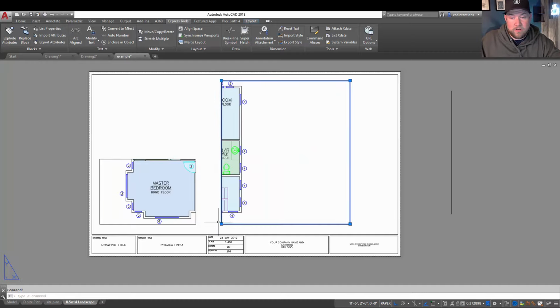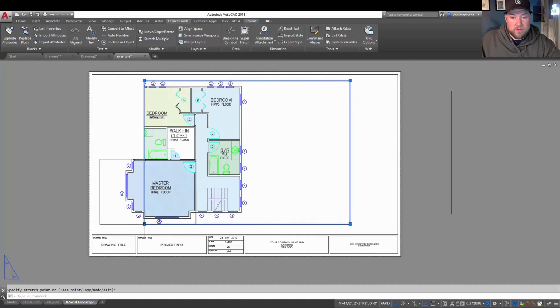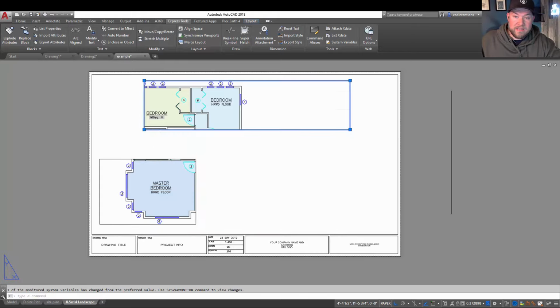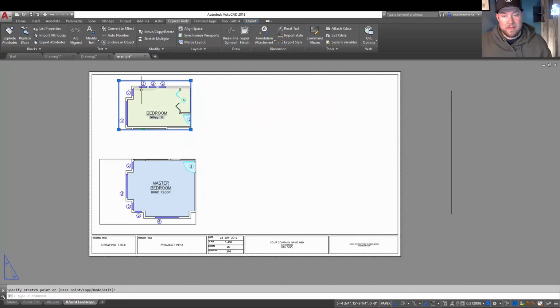Now this looks a little bit weird right now, but if we drag this viewport over, you can see that they are overlapping. So they're in the exact same position and at the exact same scale. So this can make it really quick and easy to match the scale between 2 different viewports that you may have on a layout. This also works with more than 2, and it makes it easy if you say want to split up your drawing quickly at the same scale, showing different areas or views of the same model.